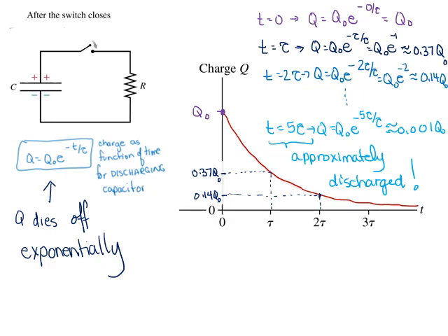So if you're working on a problem and I ask how long does it take to discharge the capacitor, I'm asking you to figure out what is the time constant, and the amount of time it takes to discharge is 5 times that time constant.